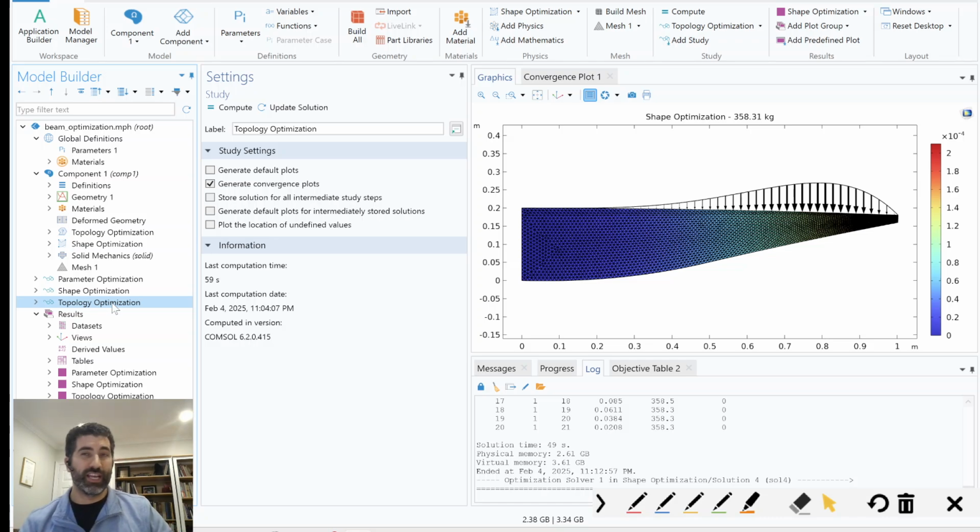So in this particular case, we're solving for the y displacement, the x displacement. We get our strain, we balance our stresses. In other models, we would look at the temperature, right? T is our field variable, concentration is a field variable, velocity in laminar flow is a field variable. We're adding in a new field variable, which is our density. And our density is really simple to understand. It's 1 where your material is actually present, and 0 where it's not present. Right? Pretty straightforward. And in between you have some kind of an interface going between them.